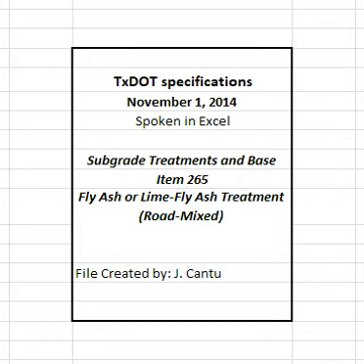4.3.4 Mixing of fly ash. Thoroughly dry mix the material and fly ash using approved equipment until a loose, homogeneous mixture is obtained. Sprinkle in accordance with Item 204, Sprinkling, as directed, to achieve adequate mixing and hydration moisture. Prevent formation of fly ash balls. 4.3.5 Final mixture. After mixing and required mellowing, the engineer may sample the mixture at roadway moisture and test in accordance with TEX-101-E, Part 3, to determine compliance with the gradation requirements in Table 1.